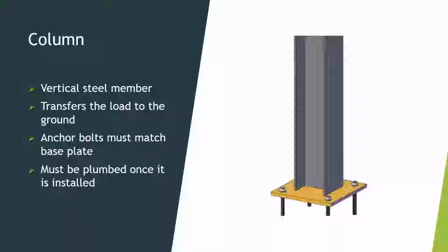Right, so when we go connecting our steel, if our column isn't plumb, none of our connections are going to match up. It's going to throw the whole structure off. Our holes are going to be off. Any welding we got to do is going to be off. It's going to leave big gaps. So right from the get-go, we got to make sure she's nice and plumb for us to start our steel structure. Great job, guys.